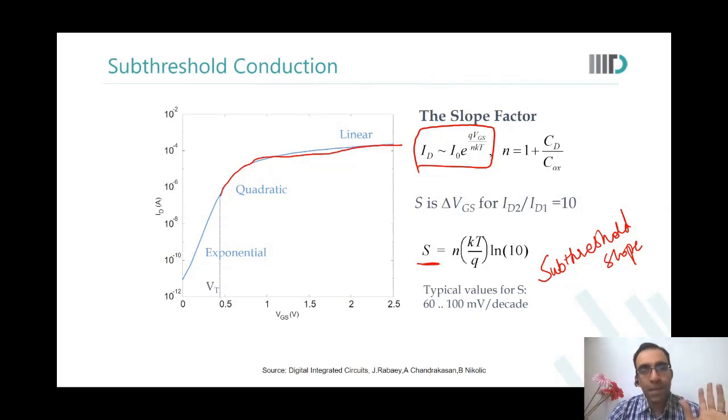So that depletion region is all connected. If some electrons enter into this depletion region, they will be at once pulled towards the drain, is it not? Yes, sir. That might happen, the minority charge carriers. So that is what the subthreshold conduction is about: even when you are not at VT, there is some band bending happening, there is some depletion region, and therefore there will be some flow of current. Yes, sir. Understood. Okay.